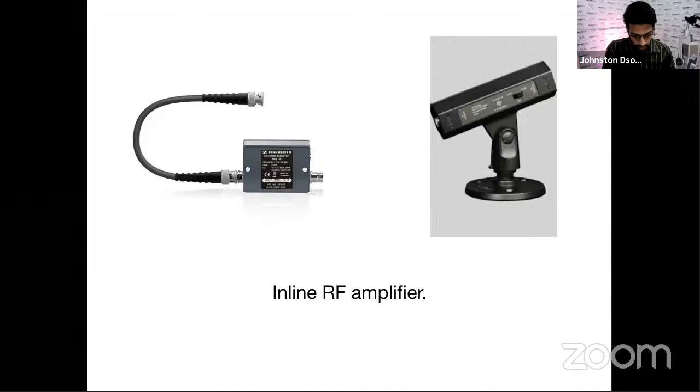Okay, it is measured in dBm. Okay, someone has asked me whether BNC is used in DTH connections. Yes, BNC is used in DTH connections also, but the impedance might be different. The cable impedance will be slightly different. What we use is 50 ohms. All right, so these are inline amplifiers which you generally use to boost the RF signal.